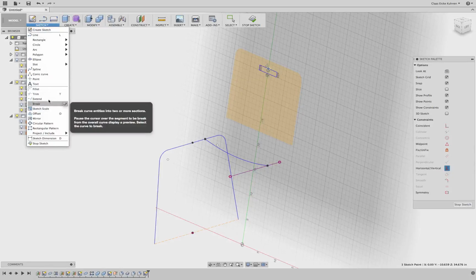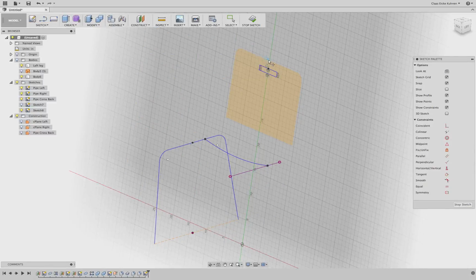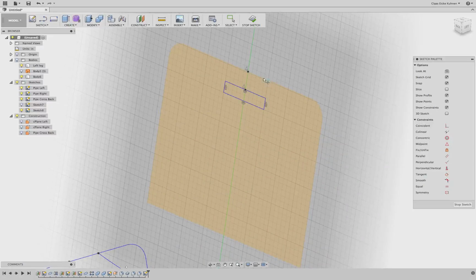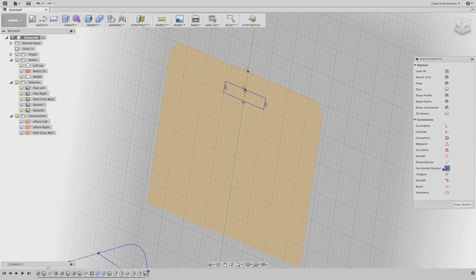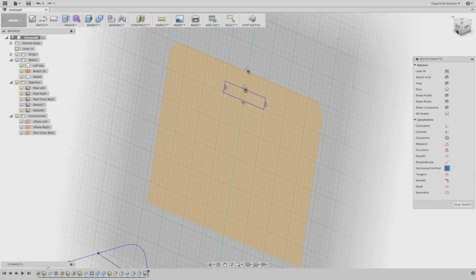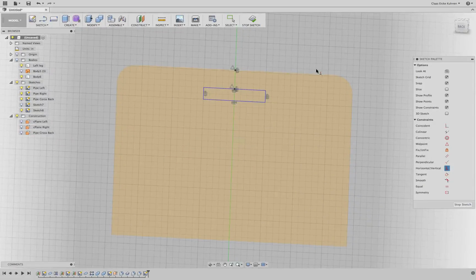Or if I want, I could also create a point on this yellow edge, which is actually coming from my 3D object, and then those two define being vertical. So now when I drag this one out, you see the other one grows symmetrically to the other side. And then maybe some dimensions, 2 inches, 6 inches.